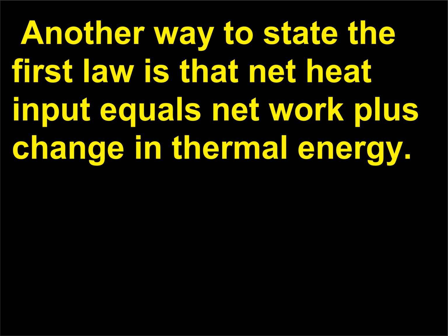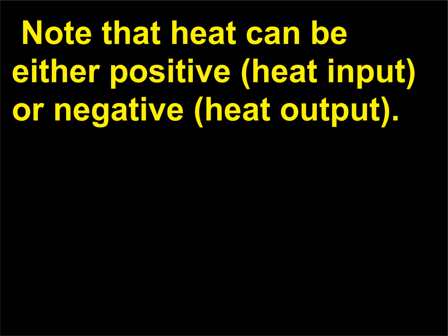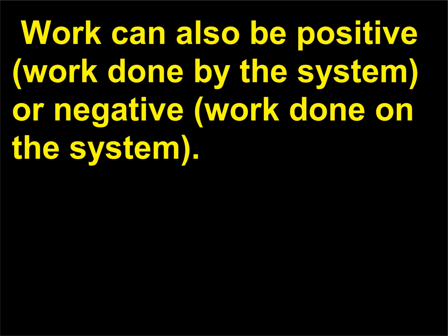Another way to state the first law is that net heat input equals net work plus change in thermal energy. Note that heat can be either positive, heat input, or negative, heat output. Work can also be positive, work done by the system, or negative, work done on the system. Thermal energy can also go up or down.